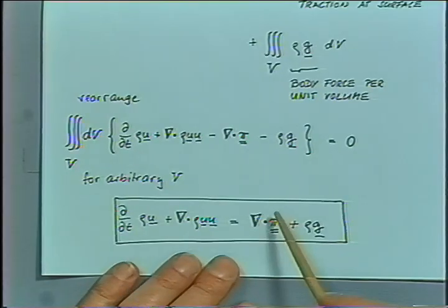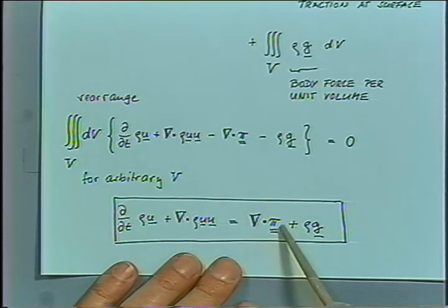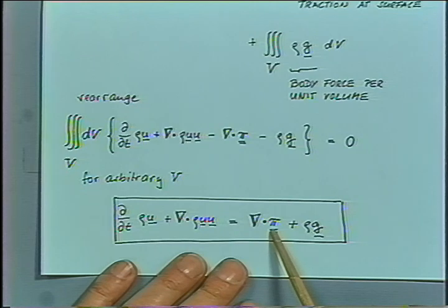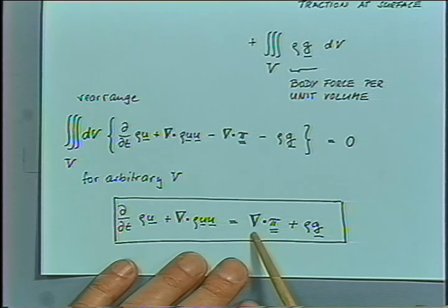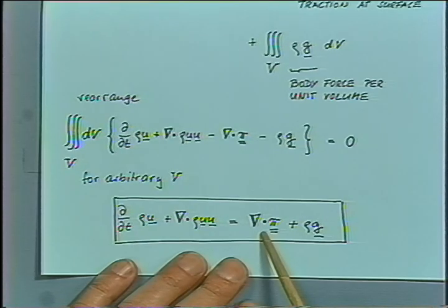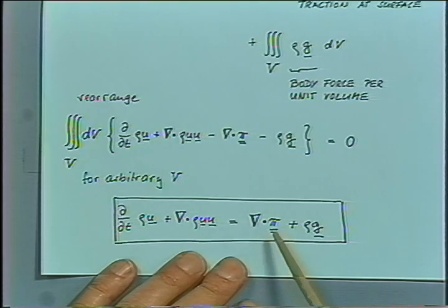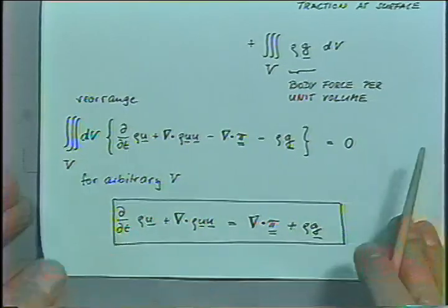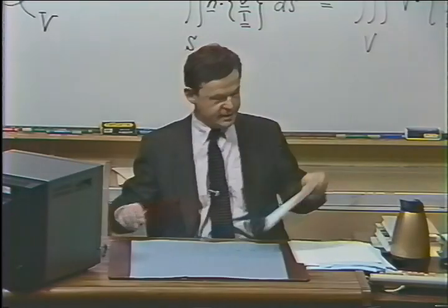And the second change in notation which you will find is that the stress tensor pi will be split into a pressure contribution, an isotropic contribution, and the deviatoric part. So this will be nabla dot p. Pressure is a scalar quantity, so the dot has no meaning in this case, it would be just the pressure gradient, plus the gradient of the stress, which would be nabla dot tau, the deviatoric. So those types of variations you will find in books, and that's okay.